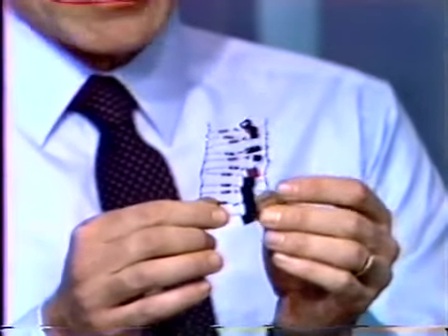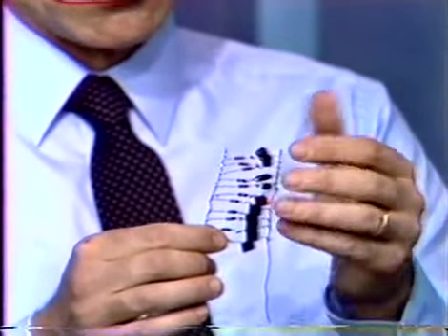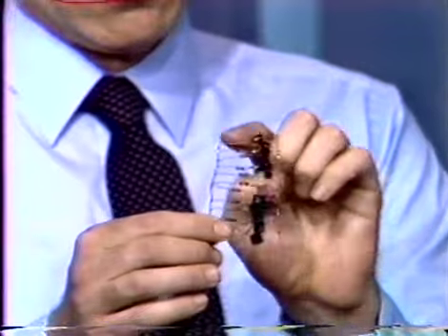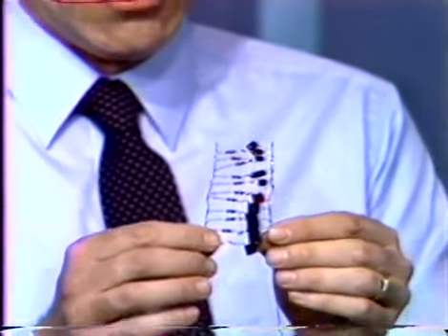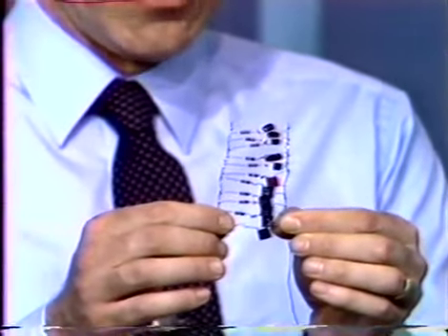they look a little bit unwieldy. This happens to be an 11-rung ladder, and what we have are, of course, simply 11 parallel RC sections. This network gives us a 1 over radical S roll-off from several megahertz to fractions of a hertz. Again, using 1 RC section per decade, we get that sort of performance with this kind of a network.